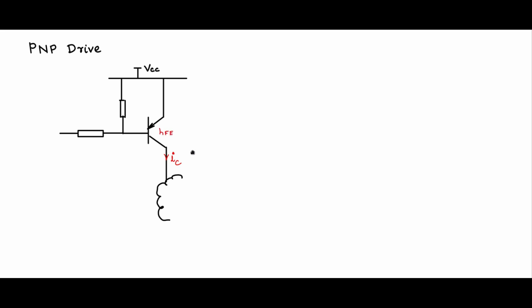And let's say the transistor has an HFE SAT, some value. IC by HFE SAT will be just the saturation value. You have to provide IB on in the base drive so that it goes deep into saturation. So IB on is 2 times IC by HFE SAT. So that value should be given here. R1 and R2 are the two resistances that you need to design, and IB on is what you should give here. So how do you choose the value of R1 and R2?